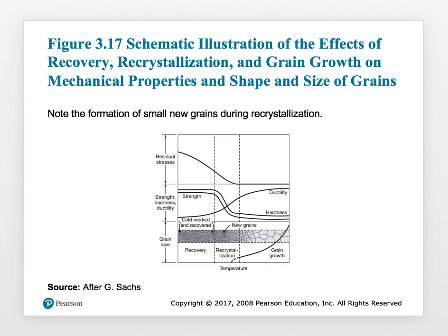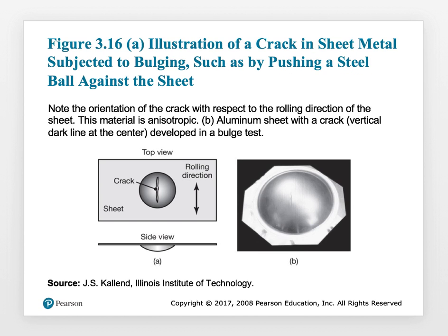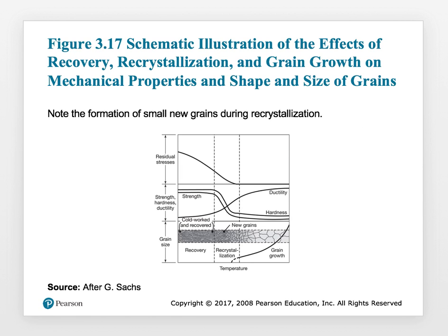So why am I trying to correlate that to a process like this? Suppose you did cold rolling, and you also try to deform it in the third direction. It can easily create a crack in that material. But suppose you want to avoid that, what would you do? You would do hot working, and then you are creating small grains, and then if you heat it up slightly, what happens to those small grains?